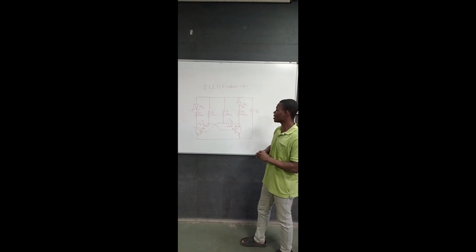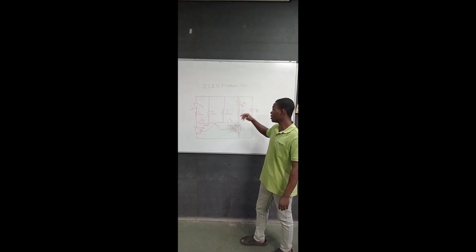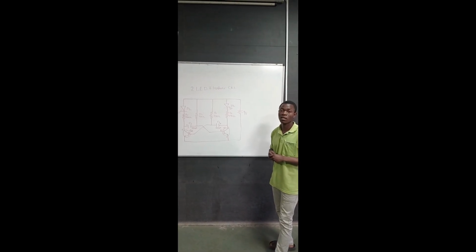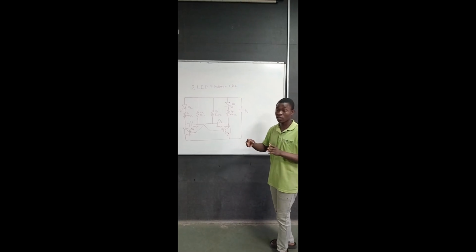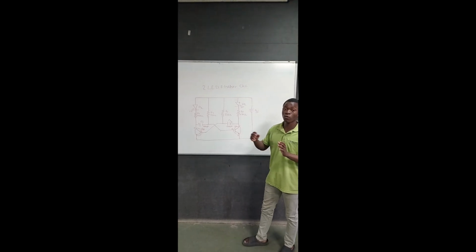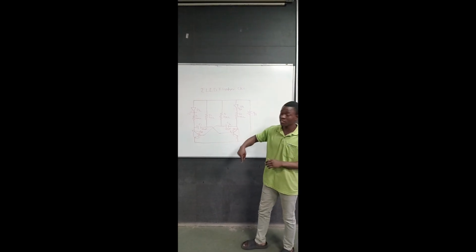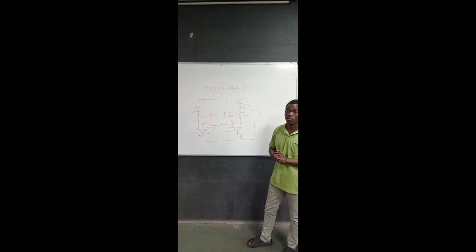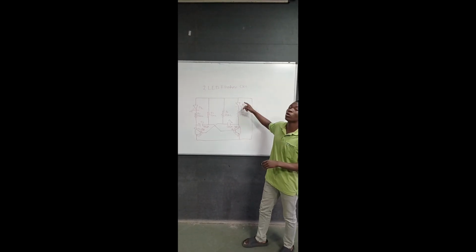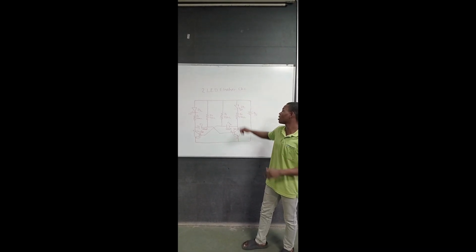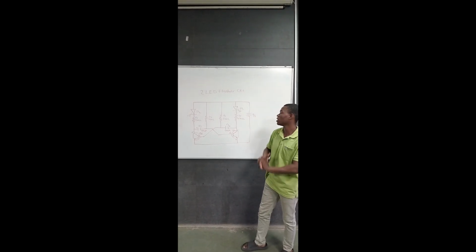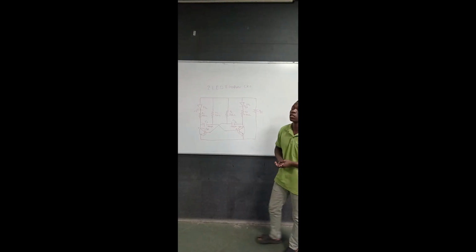Simultaneously, the capacitor on the second BJT, this one, will start charging. When the voltage of this capacitor reaches a certain voltage, it forces the first BJT to turn off and turn on the other one, causing current to flow to the corresponding light emitting diode, making it glow and light like what the first one did.